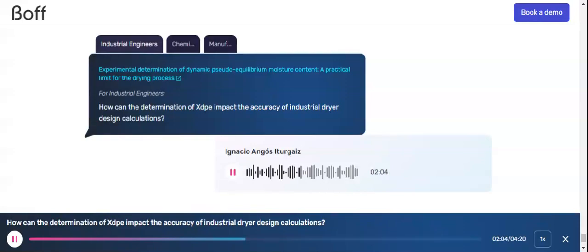The problem with the Lewis moisture ratio, which we will call theoretical, is that it assumes that the behavior of moisture during drying is monotonic until the moisture equilibrium is reached. Moisture equilibrium is the condition where a material has no change in its moisture content and begins at the equilibrium moisture content, which, once reached, does not change over time.